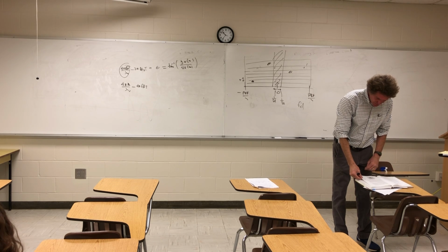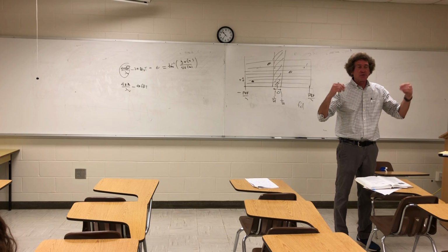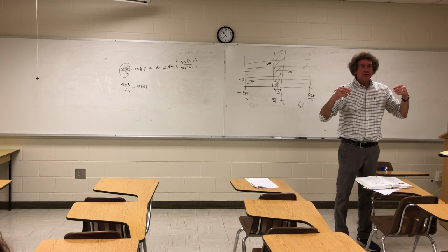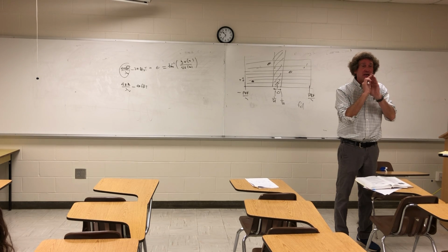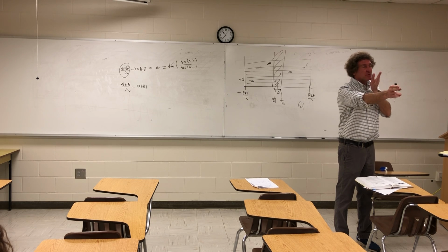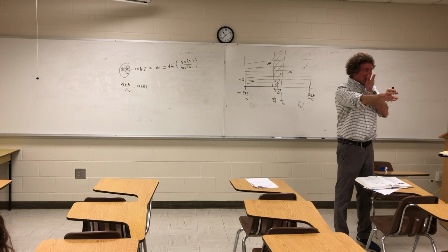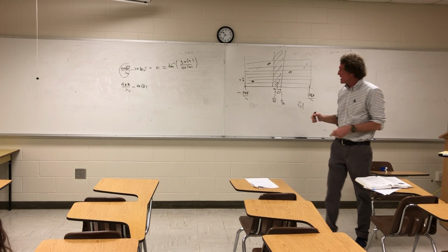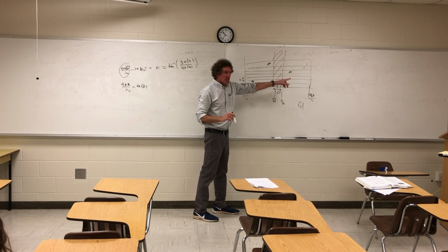On the bottom of page 295, if you look there, what he's trying to do is give you a picture, and this is for just one range bin. Follow me? It's literally we're sending out one dwell time, one pulse, one PRI going out, coming back, and now we're seeing within that one pulse where the actual targets are.